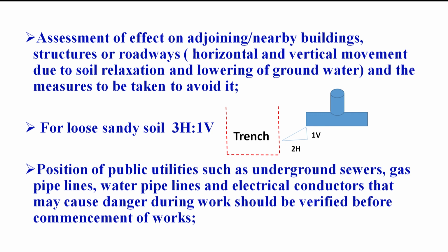So we have to analyze the soil relaxation, and because of that excavation, there may be a chance of lowering of the water table also basically. Because of that change in the depth of the water in the soil, it changes the properties of the soil basically.